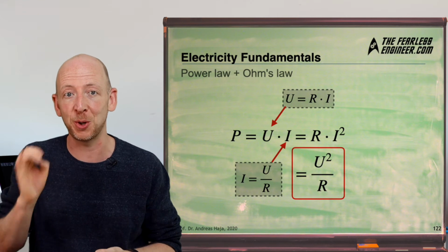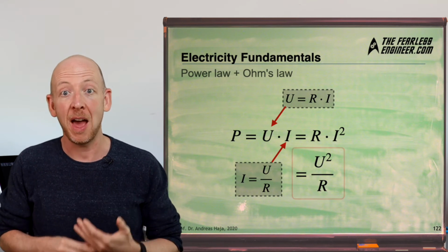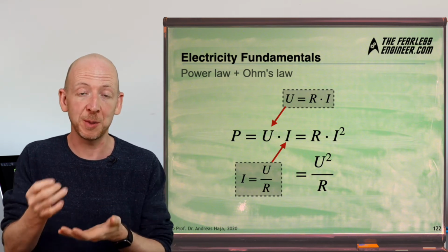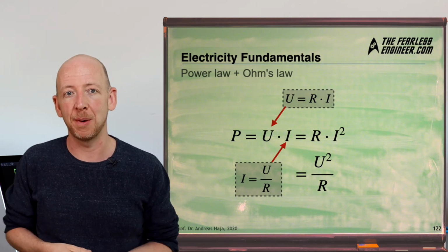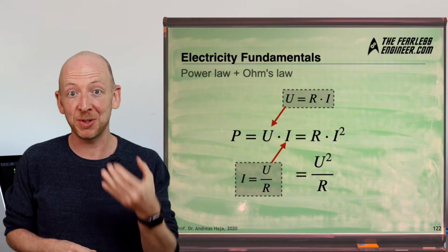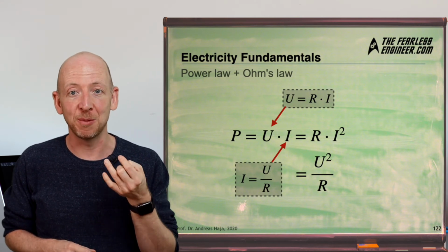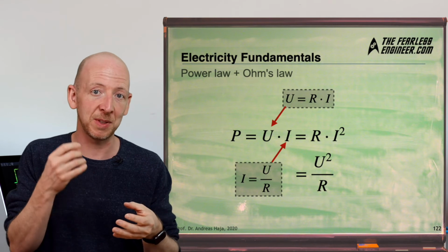And in fact, an important conclusion can be drawn from the two equations here. As voltage and current are squared, this means that if we double the voltage or current, we get a quadrupling of power. And one of the most common mistakes in the interpretation of the equations is related to the resistance, because here the two equations seem to be somewhat contradictory.